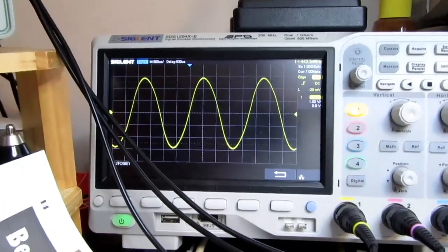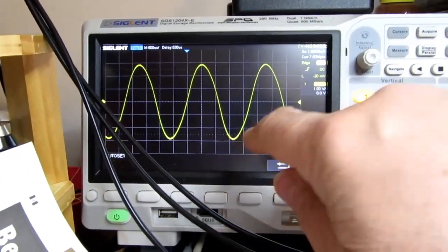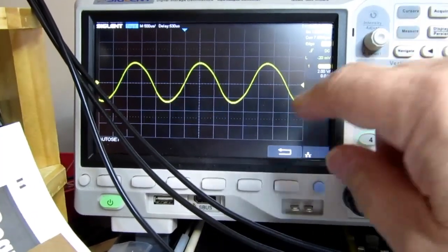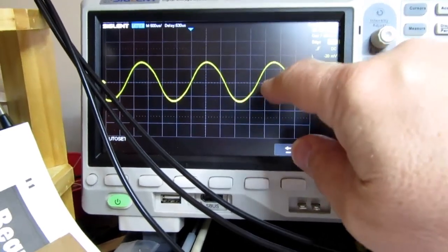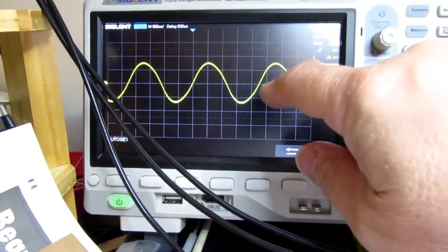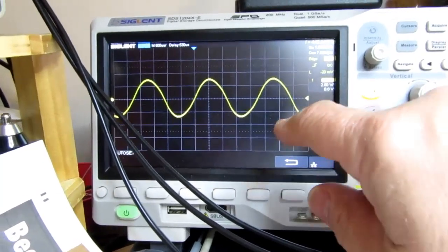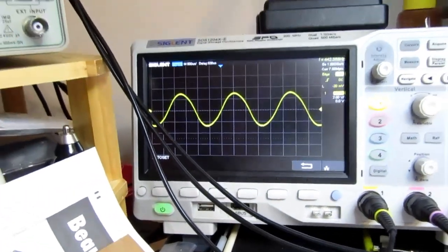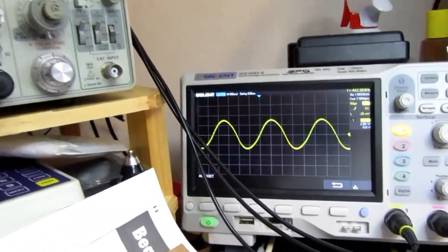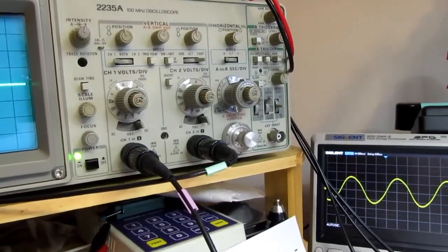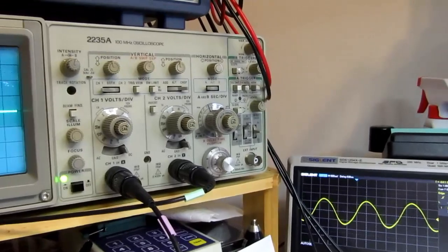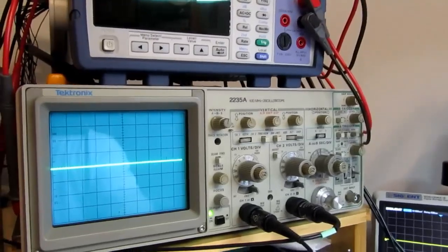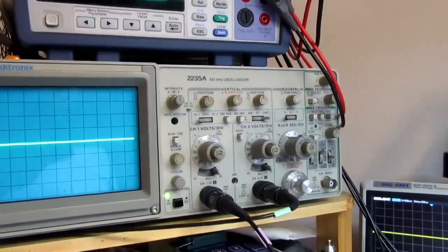And we're getting, what do I have here? Vertical, 2 volts per division, so 2.5, close to 3 volts. I'm sorry, 3 divisions at 2 volts per division, right? Is that what I'm at? Yeah. So, 6 volts thereabouts. I wish it was adjustable, both in frequency and in amplitude, with the pots on the board.